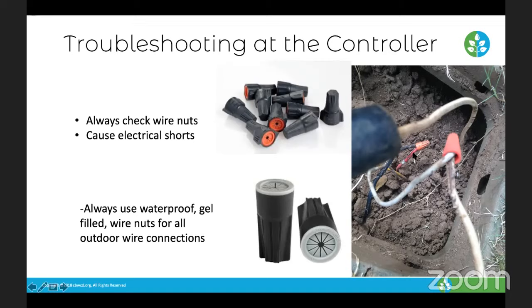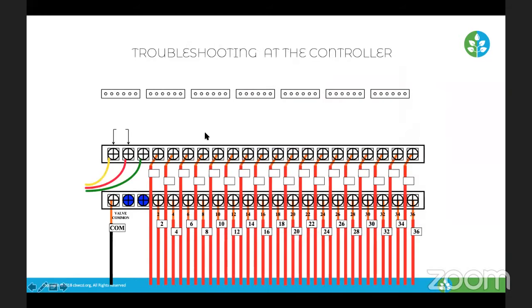If you haven't checked in a while and they don't look that good, you can simply go with your tools, your wire cutters, cut the wires, strip them till we have bare wire, twist them together, and put a brand new weatherproof cap on there. At the irrigation manifold with a grouping of the valves for residents, I'll do new wire nuts, and then I'll wrap it in electrical tape, so I know that there's not going to be any moisture going in.